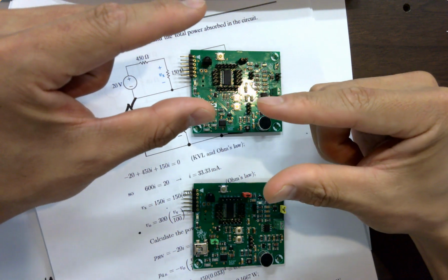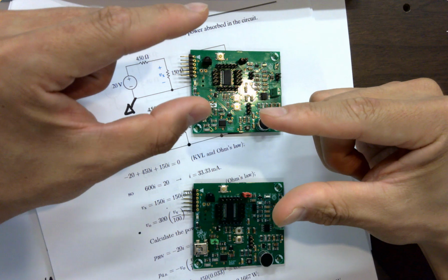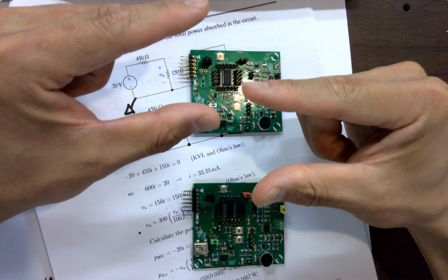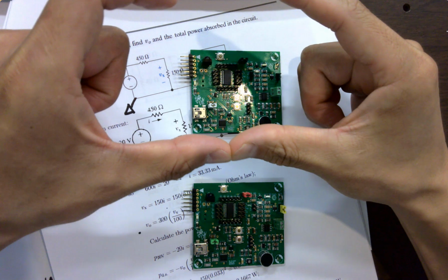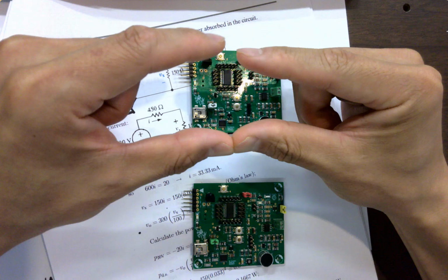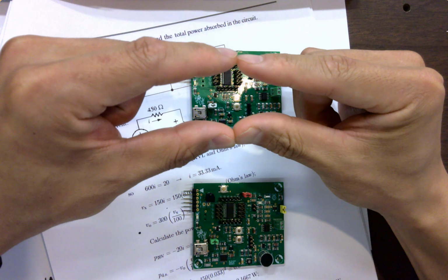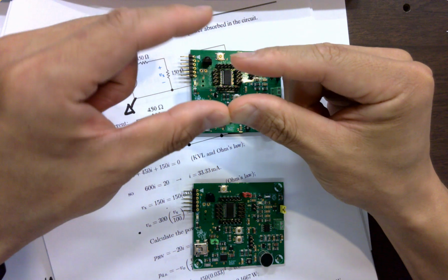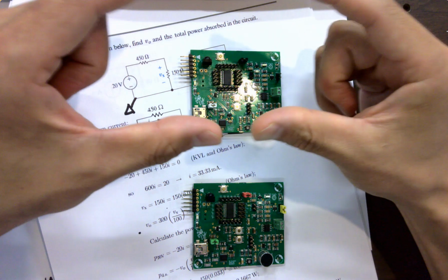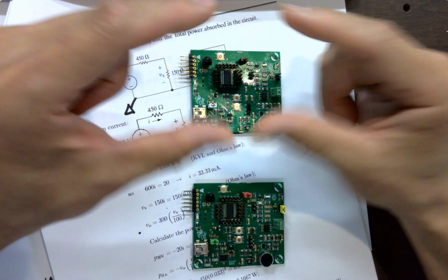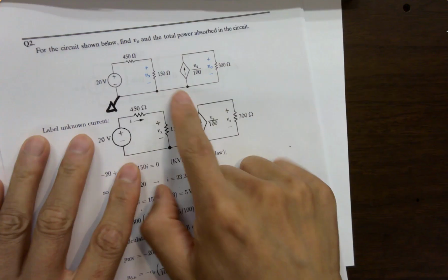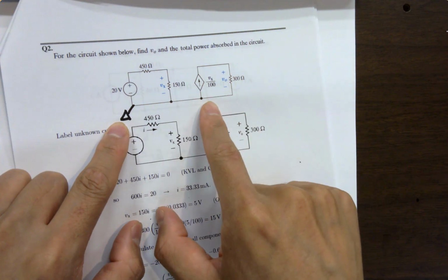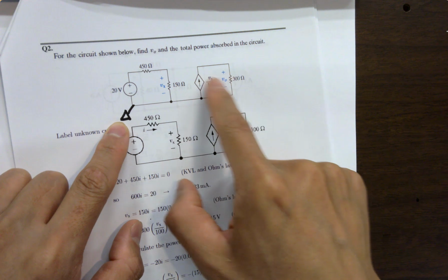However, if you bring them together and you don't have a common ground, 5 volts here is being treated as 0 volts or something else. So you have to bring the common 0 to the same voltage reference. So 5 volts here is being treated as 5 volts on the other board, so they can communicate. You send the 5 volts, it sees the 5 volts. You have to have the same baseline, same reference. So this is the same reference, right? So it's shorting both circuits. It's not communicating anything. It's not affecting anything from here to here.